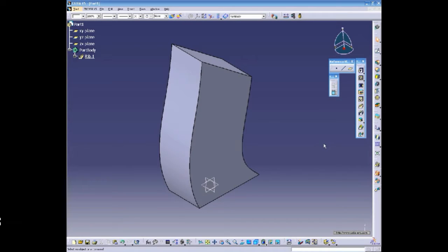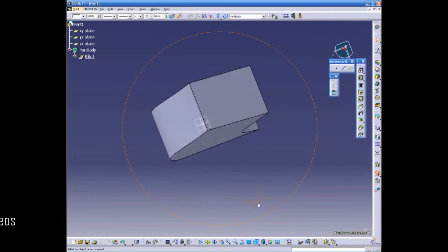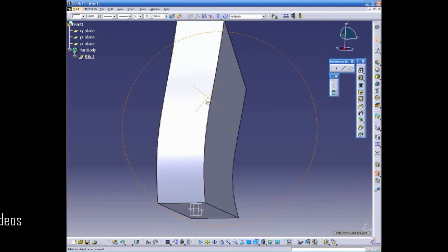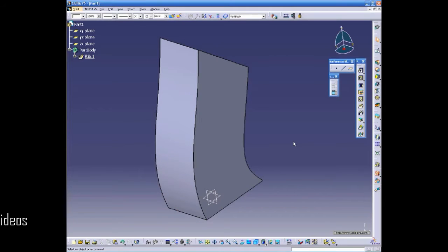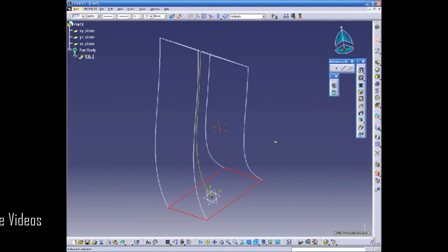In this example, I will show you the general concept for creating 3D elements. Assume we want to create this geometry. Then we need to have first a 2D element called profile, which should be swept out on another 2D geometry called guide curve.